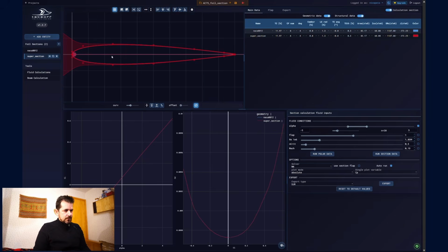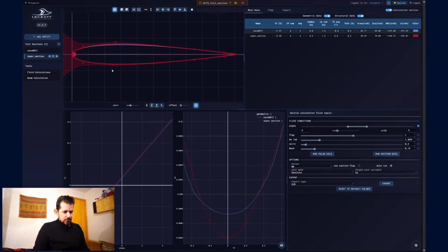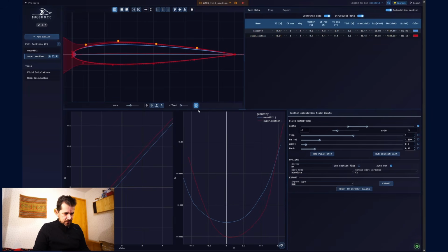Okay, so these are control points. We can start dragging the control points, and we'll see if we've improved the CL or not. Where we want to go is CL 0.2, 0.4. So we said in this line, we want to be better than the reference. Let's try to play a little bit with it. We're going to move the control points.